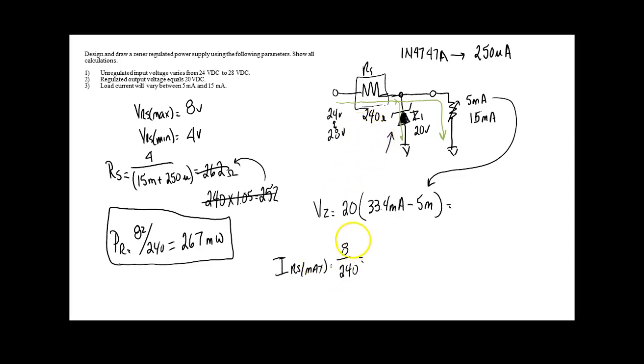So we took the maximum voltage. So when is the current flow maximum? Well, when the voltage drop is maximum. So I took the maximum voltage that we would drop, then I divided it by the size of the resistor that we calculated. I didn't put that out here. Now that gives me the maximum current flow in the circuit. Okay, so right here we have 33.4 milliamps. Well, Kirchhoff's current law says the sum of the currents in the parallel branches has to equal the applied current.